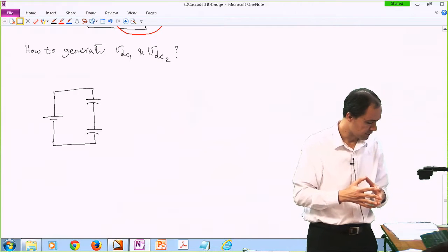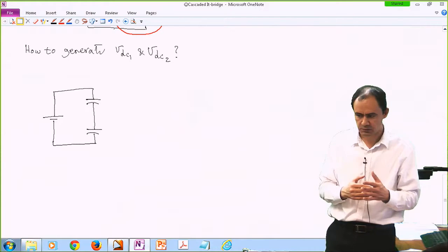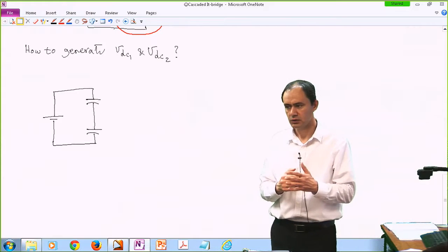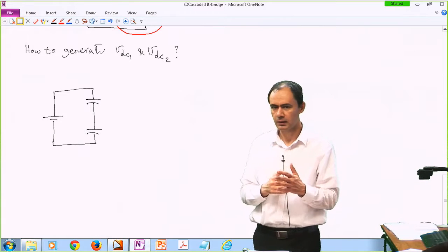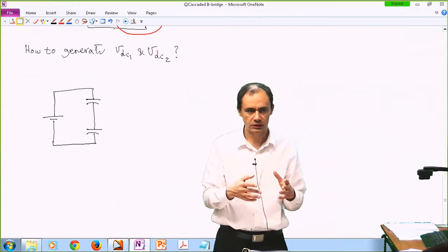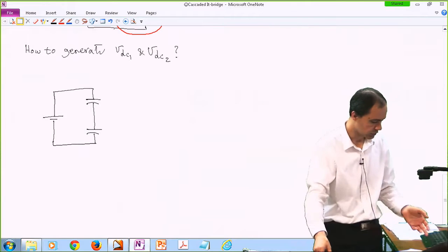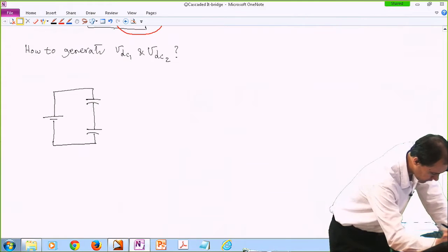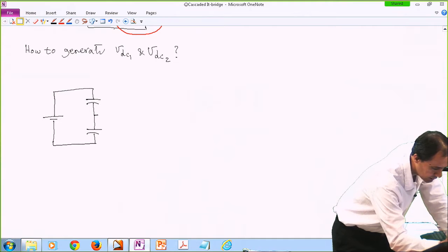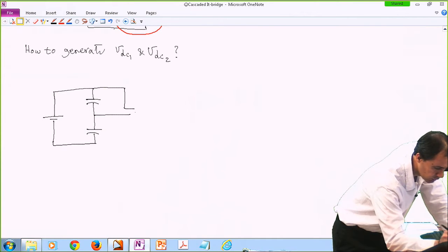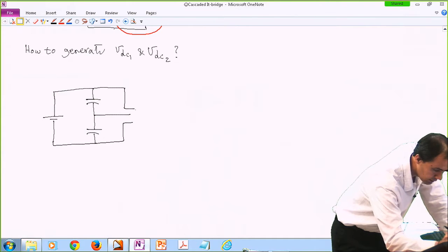In terms of what size capacitor we should use, you should look at the amount of electric current that is charging and discharging these capacitors, as well as the switching frequency, basically the amount of charge and discharge, and make a decision. So basically those determine the ripple in the system, the ripple of these voltages.